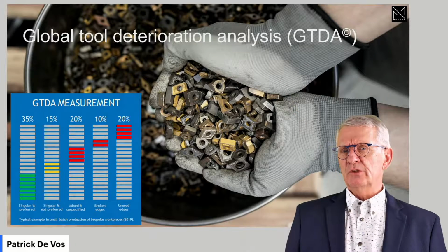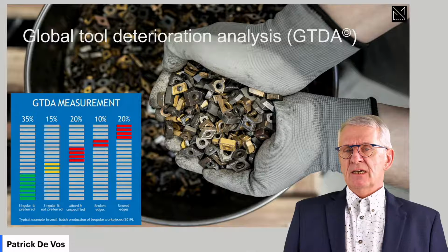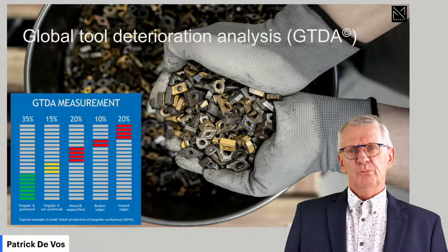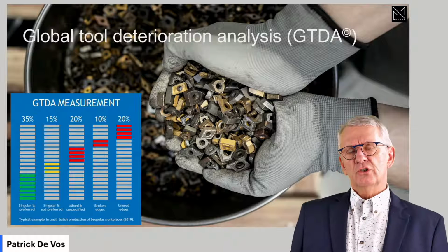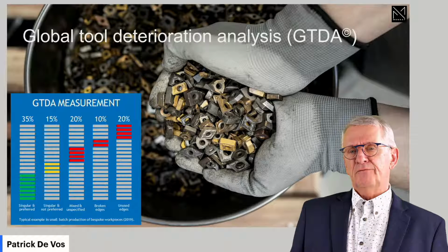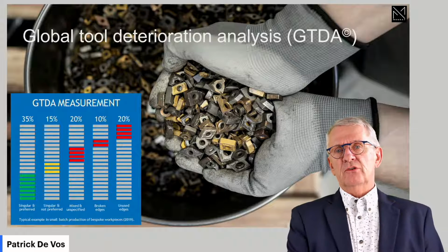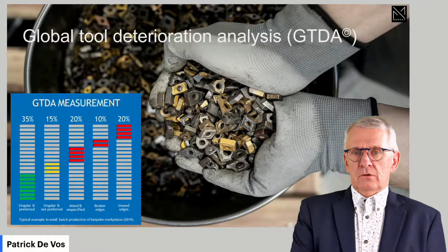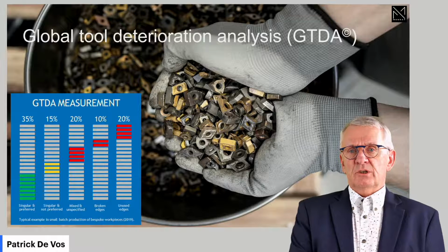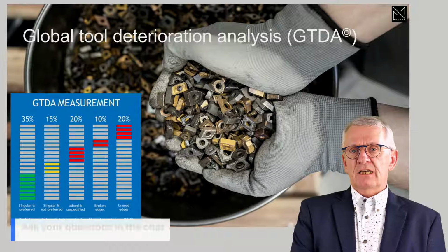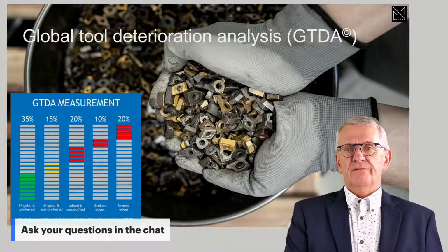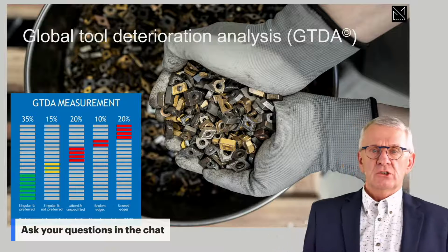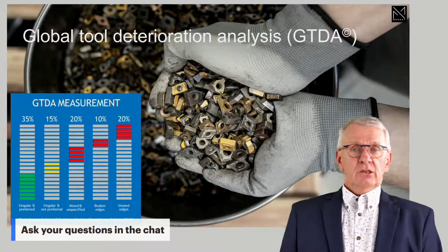In small batch production, however, life is a bit more difficult because then you have a situation. You could use the tool for 20 minutes, but after 5 minutes, the batch you need to do is over and done with. And then what do you do with the tool? You throw it away because the job is done, or you keep it, but then you have to keep it in such a way that for the next application you know how far the wear was, and so on and so forth. Here it's a little bit more difficult.